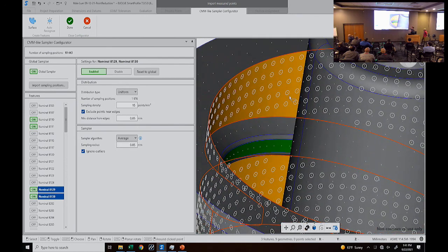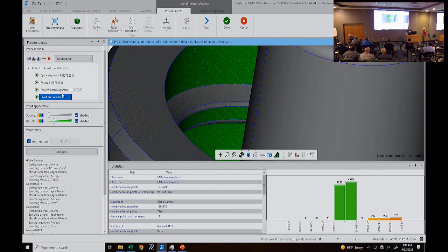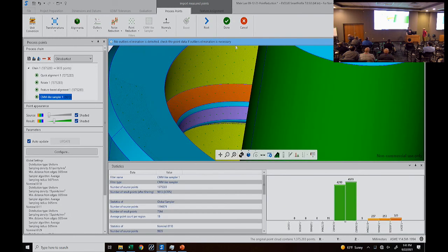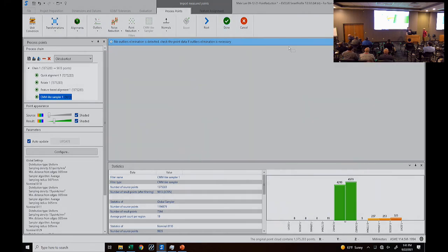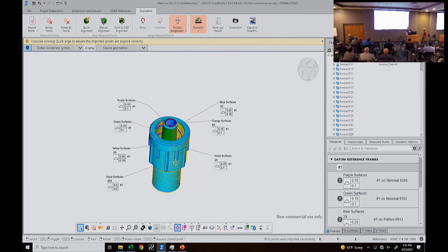We can see all of these individual points with some radius around them, where we're going to average our CT data in that space. So I have control over those points to say I really want to increase my sampling radius, and I get larger averaging circles, basically. So I can step out of that and confirm I have a total of 9,600 points at the end here that I will bring in for my analysis.